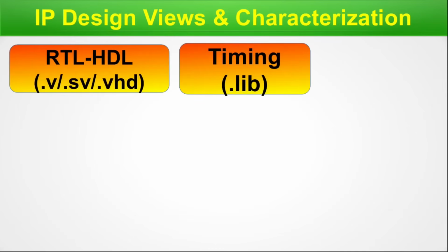The timing library characterization is one of the most popular, also you can call famous, job titles. For standard cells, we call this standard cell characterization. At this stage, dynamic timing analysis is performed using Liberate or SiliconSmart EDA software for the standard cell library. The dynamic timing analysis at the unit cell level is a set of SPICE simulations from which the rise time, fall time, delay, slew, load, all these data are collected and put in Liberty format, that is .lib.